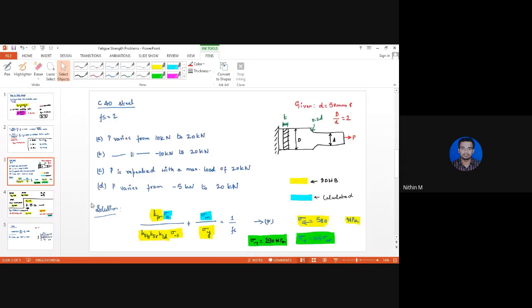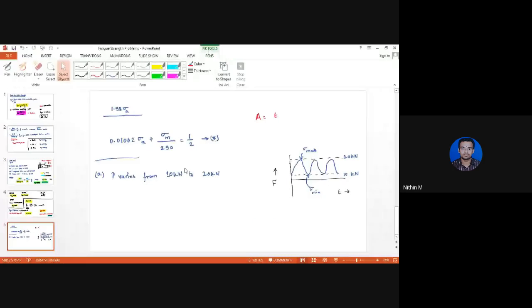So thereby now, the area of the component will be equal to d, that is lowercase d, multiplied by t, right? So this is the cross-sectional area of the component. Since the load acting on the component is axial in nature, the formula to calculate stress induced in the component is given by F by A. Now, what is the maximum stress?